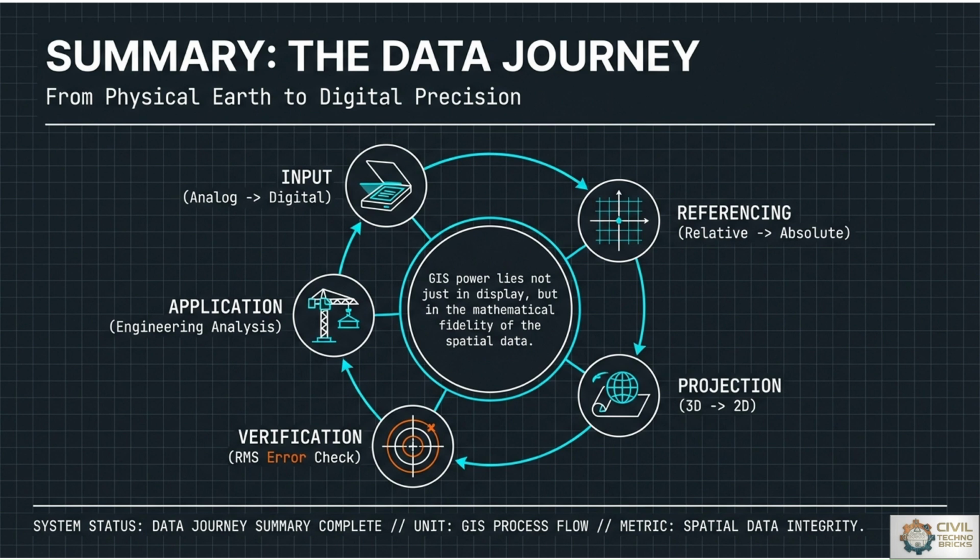So not a single projection is perfect. They have minute errors or distortion in between them. From the civil engineer's point of view, choosing the right projection is a high-stakes decision. If we are using a projection that distorts distance for a multi-kilometer highway project, your material calculation and alignment curves will be mathematically incorrect.